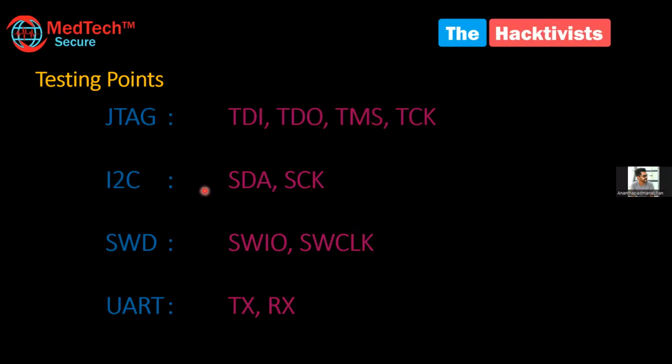what we discussed. As I told, in the JTAG protocol, we mainly look into the TDI, TDO, TMS, and TCK points. Suppose just imagine I got a device and we have to analyze that device. If it is using a JTAG interface, we have to find out these 4 points in that particular device to find out what communication is happening in that protocol.